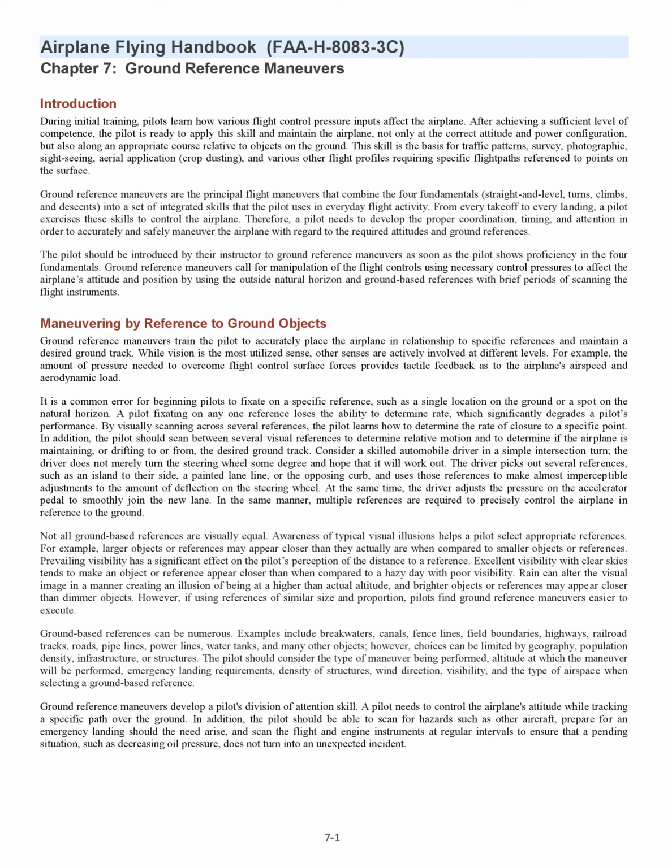This skill is the basis for traffic patterns, survey, photographic, sightseeing, aerial application, prop dusting, and various other flight profiles requiring specific flight paths in reference to points on the surface. Ground reference maneuvers are the principal flight maneuvers that combine the four fundamentals, straight and level, turns, climbs, and descents, into a set of integrated skills that the pilot uses in everyday flight activity. From every takeoff to every landing, a pilot exercises these skills to control the airplane.